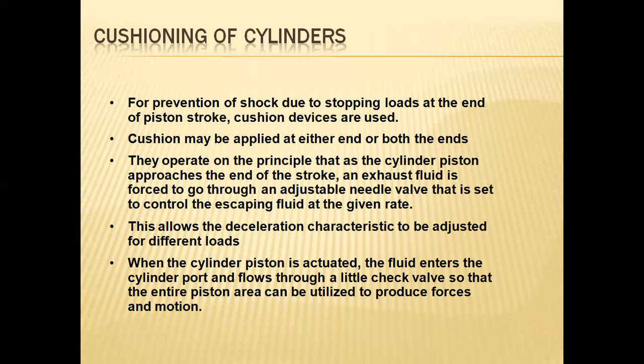Obviously, it is operated on the principle that as the cylinder piston approaches the end of the stroke, an exhaust fluid is forced to go through an adjustable needle valve, which is set to control the escaping fluid at a given rate.